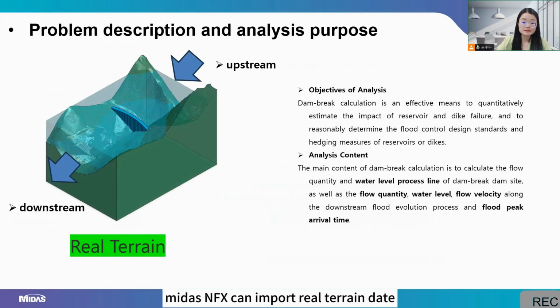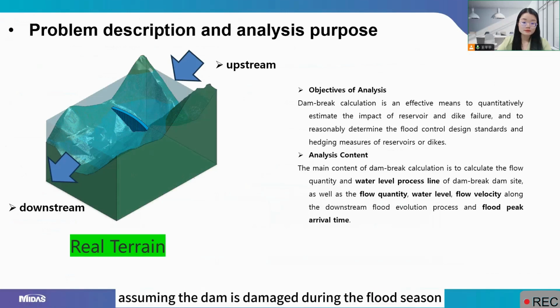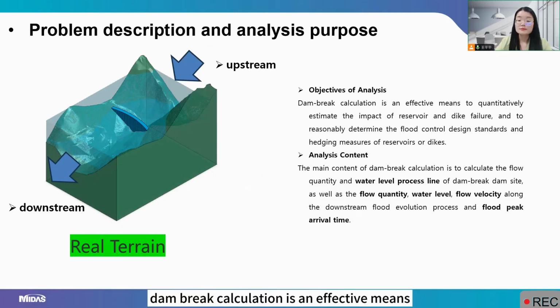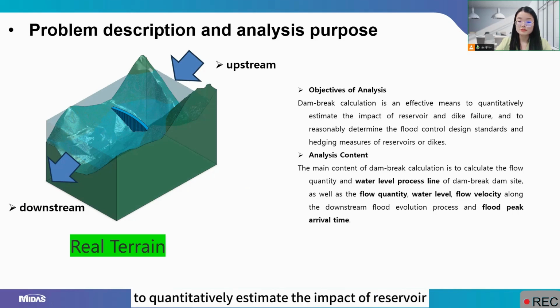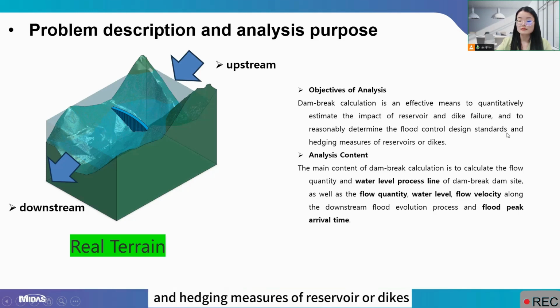Midas NFX can import real terrain data. Assuming the dam is damaged during the flood season, this case study analyzes the upstream reservoir water flow path after the dam is damaged. Dam break calculation is an effective means to quantitatively estimate the impact of reservoir and that volume and to reasonably determine the flood control design standards and the hedging measure of reservoir.